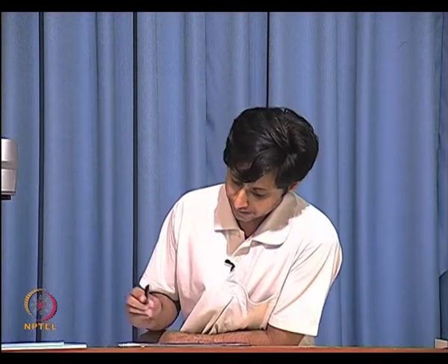Okay. Also, if the resistance is more, then the Q of the network becomes more. If the resistance had not been there, then you would basically see a perpetual sinusoid oscillation as a response. Now, there is resistance. So, as a result it is going to be a damped oscillation. The less this resistance is, the less the damping is going to be.